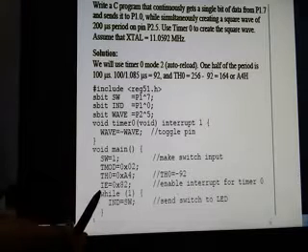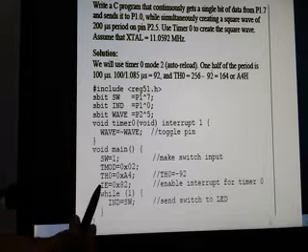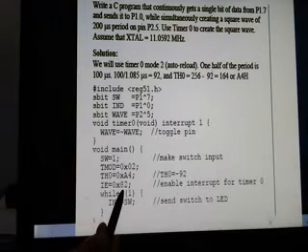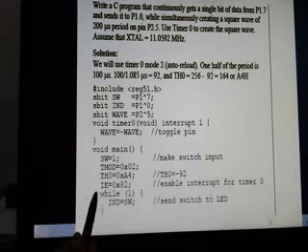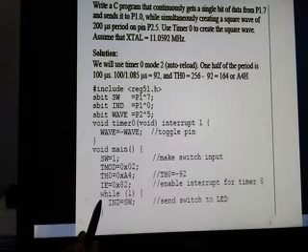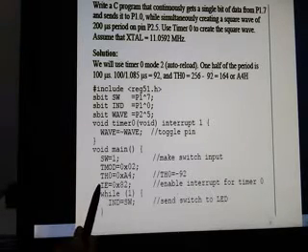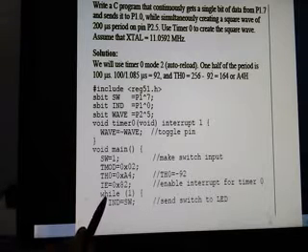IE is not drawn over here. We know how to configure IE by now. So IE will have the value 82 for timer 0. Okay, and then starting the timer we have to do. While 1, what we'll do in while 1? Okay, what we have to do here, there is one statement that is missing, that is start the timer. So you'll also give TR1 equal to TR0 equal to 1. After that you will give while 1.